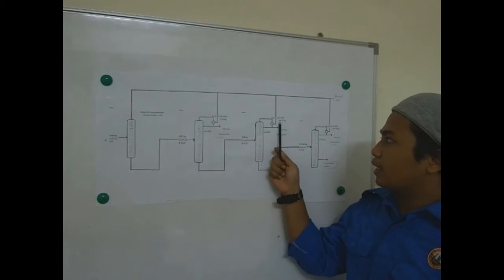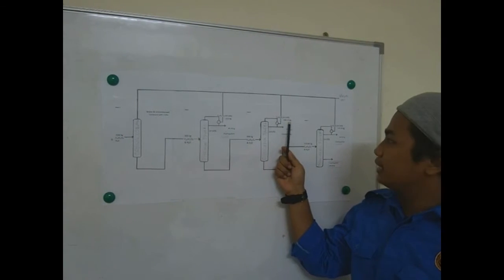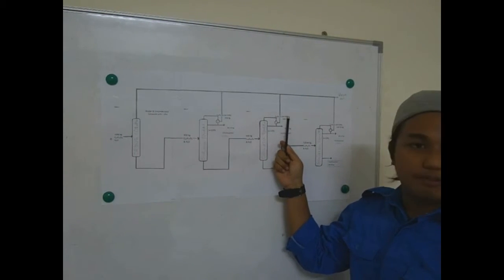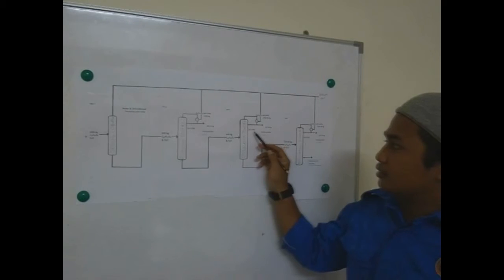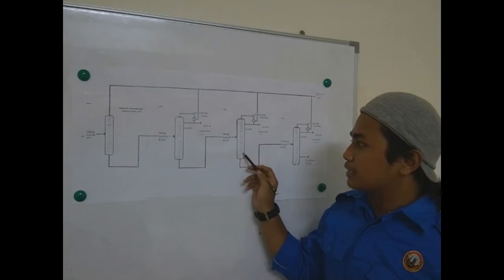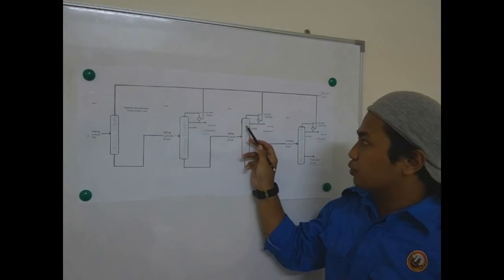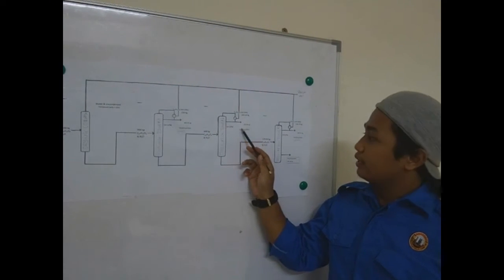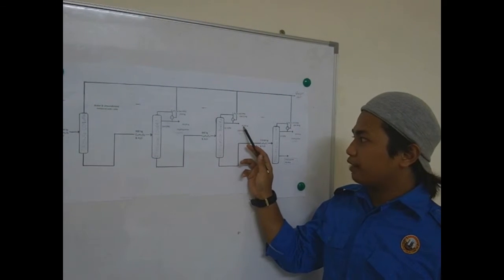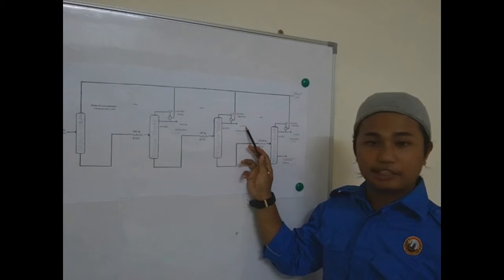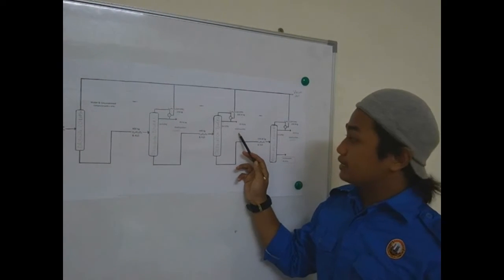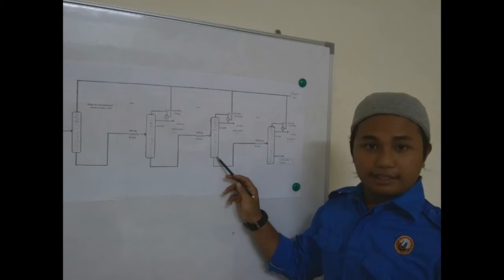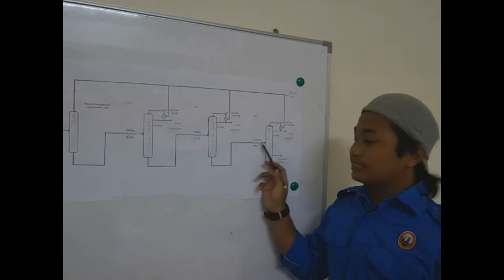Okay, for the material balance in distillation tower 2, the undistilled product that will enter the vacuum unit is 164.16 kg, which is 24%, and 12% will enter back into the distillation tower 2. For the product, which is CB, it is 405.746 kg, which is caprylic acid, and the rest will enter distillation tower 3.